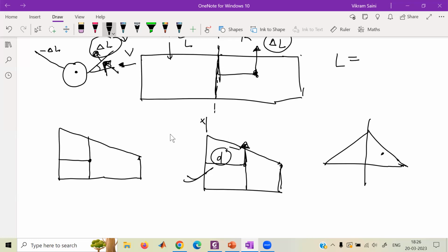Sir, we need two things. First is the taper ratio. What is the taper ratio of the wing? And second is the sweep angle. Very good. So let's say I give you a sweep angle of, let's say, some gamma. I also give you a root chord and the tip chord and the lambda, which is CT divided by CR. So this is the taper ratio, this is gamma. Now tell us what is the answer for the mean aerodynamic chord and the location of the aerodynamic center.